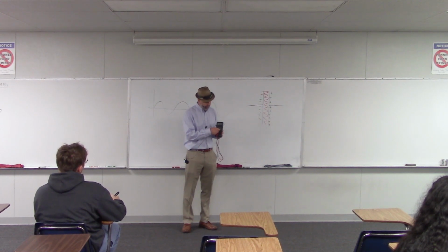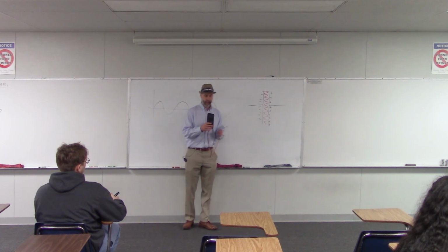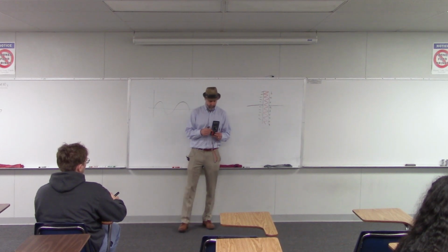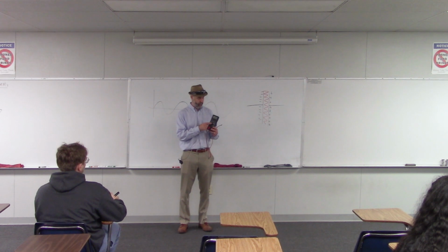And then the dial could be in one of two settings. It could go in the 20 milliamp setting or the 200 milliamp setting. So in the low current position, the meter could measure up to 200 milliamps. If you wanted to measure more than 200 milliamps, you need to move this red lead over to the far left-hand port, and then you can measure up to 10 amps.